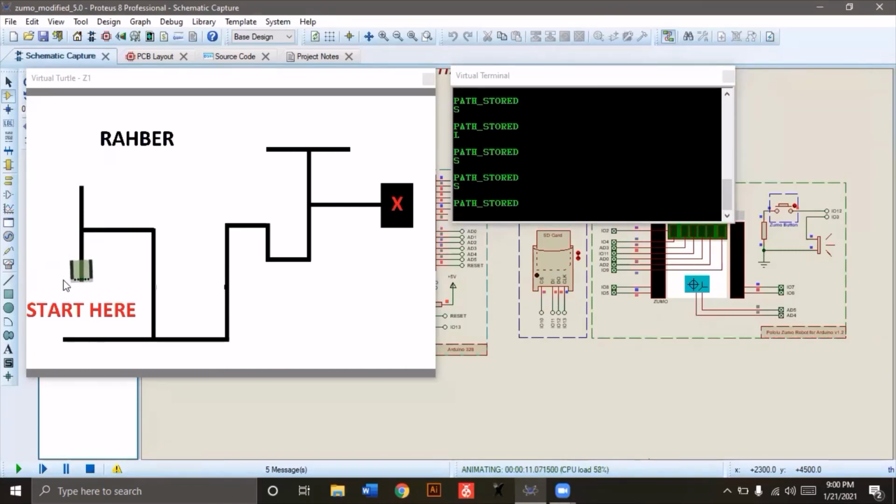So whenever there is no sensor in front of it, it will turn 180 degrees, and then it will find the black line and just follow that path. After that, it will turn 180 degrees. Now we made a condition that it will go straight if any one of the 4 sensors is on the black line. So if any one of the 1, 2, 3, 4 is on the black line, it will go straight. And for the right, it will turn 270 degrees.